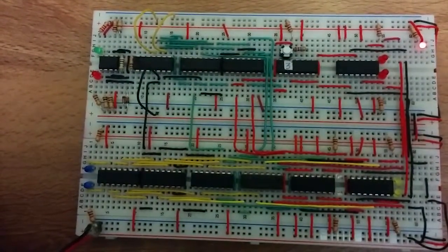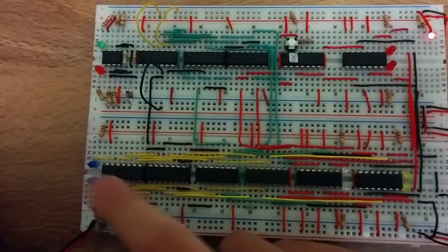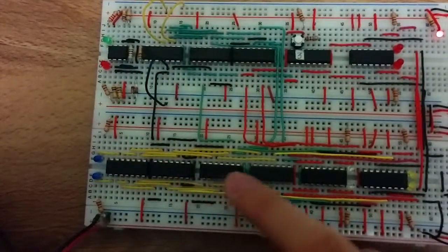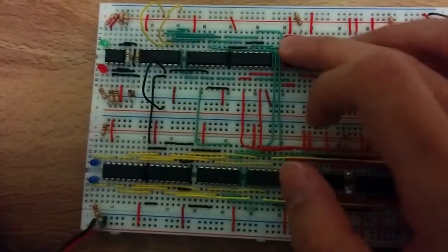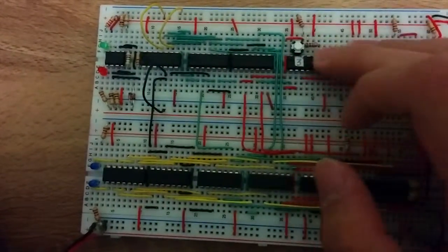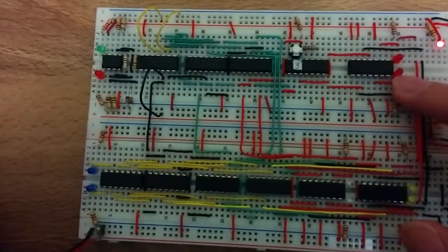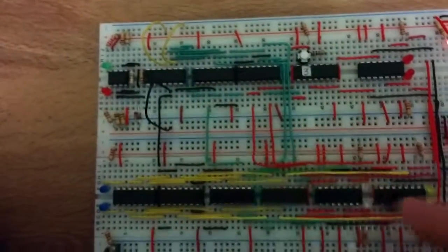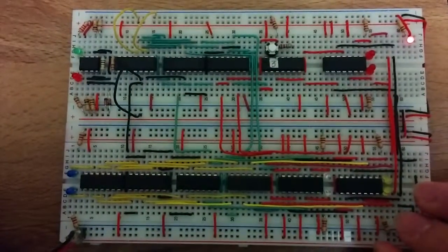Our decoder is represented by the yellow wire and connected to the blue LEDs at the end. And finally, we have our clock button at the top. Whenever it is pushed, it determines when the information from the address leads and data leads should be stored into the respective memory cells.